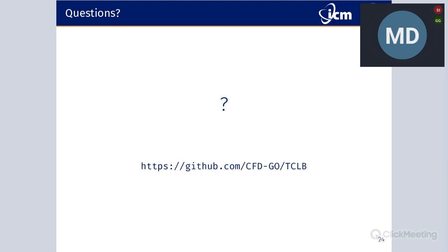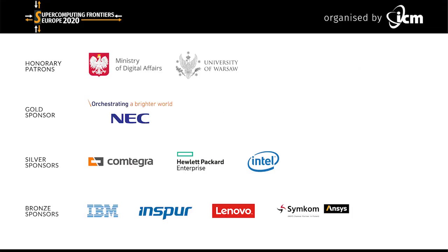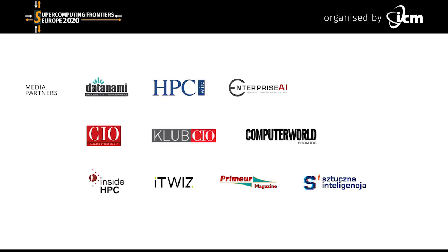Our solver is capable of optimization, so that's the adjoint part. We can generate the direct code and the adjoint part. This is discrete adjoint, and we use it directly for optimization, for example drag optimization or heat transfer optimization. So the adjoint is sort of an extra to the code. It's not part of the numerical method itself.